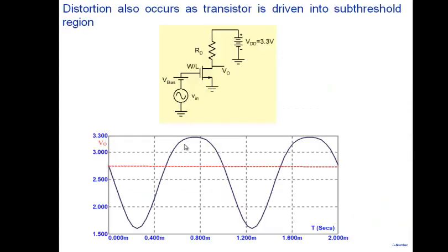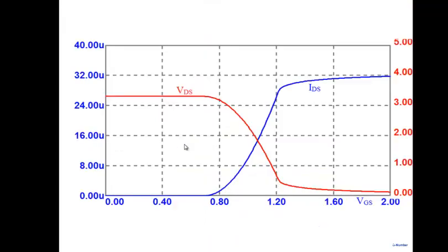Okay? Alright. The current increases with VGS like a square, and then after a while the current doesn't increase with VGS, it's going into triode region. So that's where there's an absolute limit on how large a current you can go. That's decided by the supply voltage. Because supply voltage is fixed, you can't have any value of current.